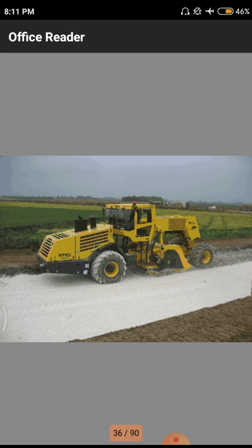This is the process of how lime is used for stabilization. Normally here we have a mixing equipment. This equipment will spread the total content of lime on the soil, and after that it moves and mixes in an even manner, so that the lime mixes with the surrounding soil very easily.